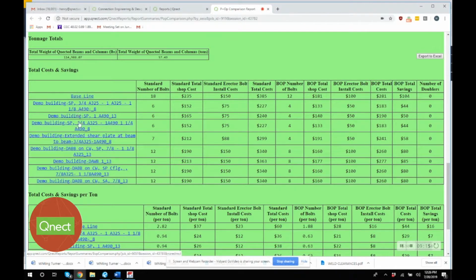And then we have 8 additional runs using shear plates, with A490 bolts, double angle welded bolted. We're not limited to this group. This is a default setting. And often this informs other ideas of trial joint configurations, and so you can run as many as you feel necessary to get to the right joint configuration without any additional costs.